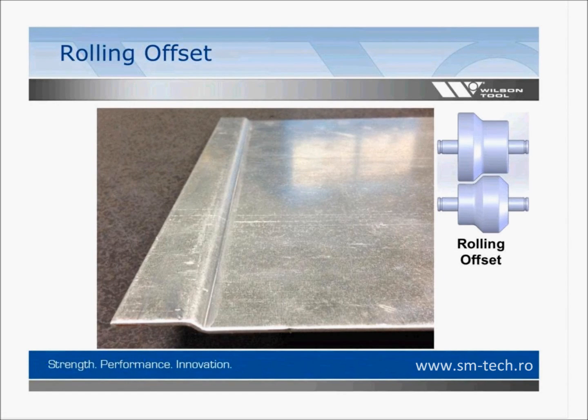So the rolling offset, there's what it looks like on a straight line. So that'd be a kind of the basic use for the rolling offset tool, just basically to replace an offset tool in your press brake. And it can be very effective at that. As you know, in the fabrication world, an offset in a straight line in a press brake is generally a dedicated setup or a unique setup on the machine. So it's quite time consuming on the press brake. If you can get that offset done while it's on the punch press, that can be a huge time savings.